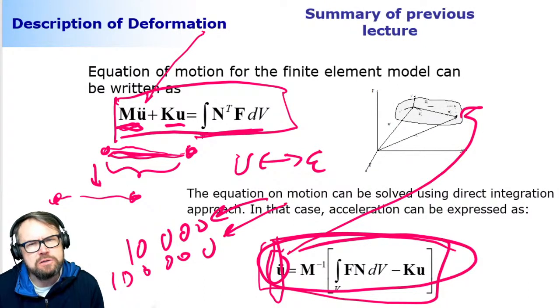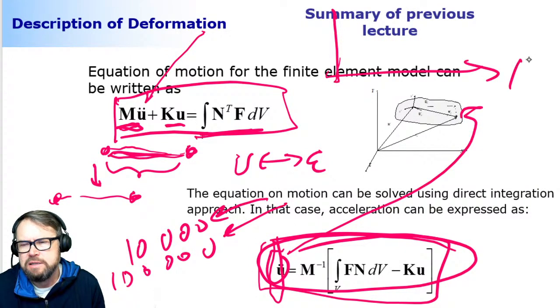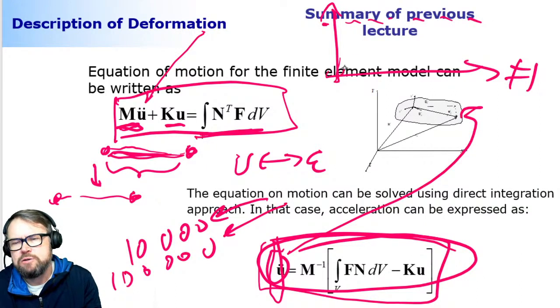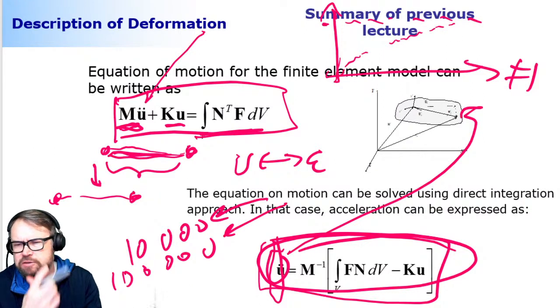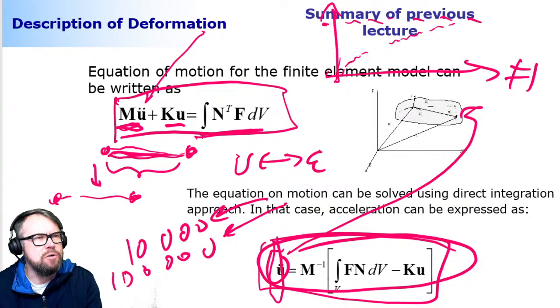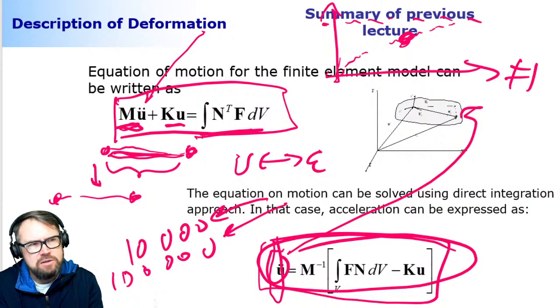And what we could do, if we're thinking about what is theoretically possible, well, we could use a coarse mesh. We could reduce the number of elements. That's possible. But remember the nature of finite element modeling: if this is a solution that you're aiming for, you get a better and better solution when you're increasing the number of elements. So that's kind of a dead end. Because if you say, okay, I want to make this computationally more efficient by using fewer elements, you end up with a solution that is not correct, not according to reality. So that's not a good choice.